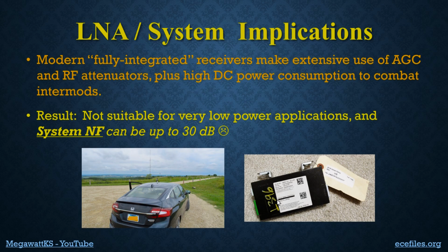For example, I recently bought the radio that is used in my car here, and I'm going to do a teardown video in the future to show you kind of what's inside it. But they can burn up to an amp or something, and you can't really do that in low power applications, portable stuff that runs on small batteries. So this solution is not really suitable for low power applications, and the system noise figure, because of that attenuator, can be up to 30 dB. Wow.